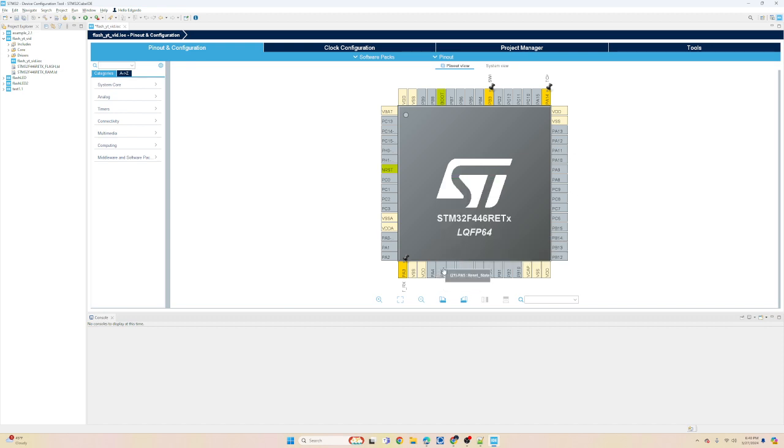And here I'm gonna reset, I'm gonna gray this one out so I can show you. So, since we're gonna be sending a command out, it's gonna be the general purpose input output, and I'm gonna have it as an output. It's gonna be green. So from here, you're gonna save it. Save. And it's gonna ask you to generate code for you. So see, here you don't have to bother with it, it's gonna basically make 90% of the code.